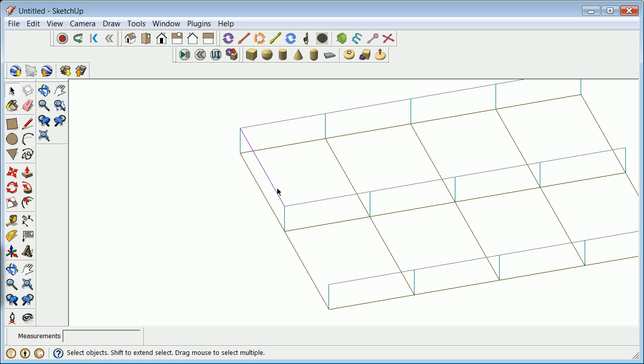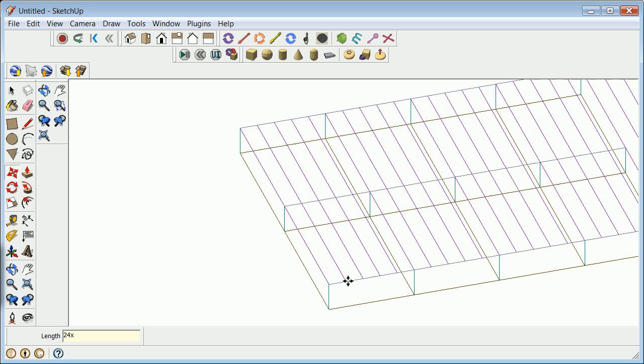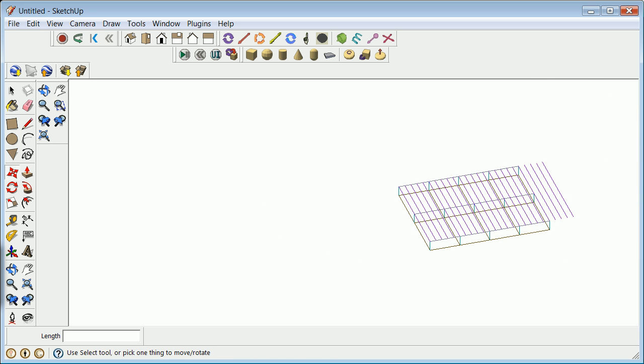Once again, I'm going to take this now and I'm going to go ahead and take my control there. Those of you who had me on AutoCAD ages ago remember that phrase. Anytime you see a repeating shape, think block. It's even more important in this, it's think component. So I'm going to now grab that, hit my control key. I'm going to move over 6 feet, which is my beam spacing, and then I'm not even going to count. That's probably 24 times. It's more than I need, I think. I'm going to go out here.